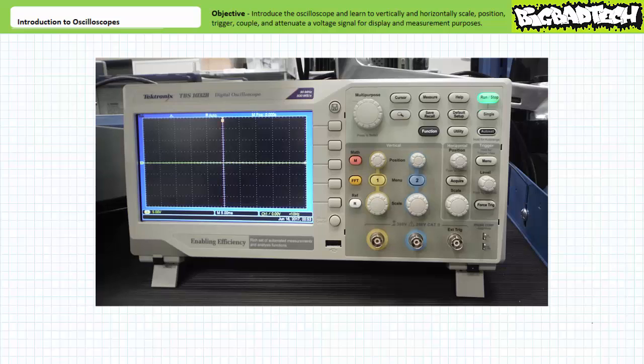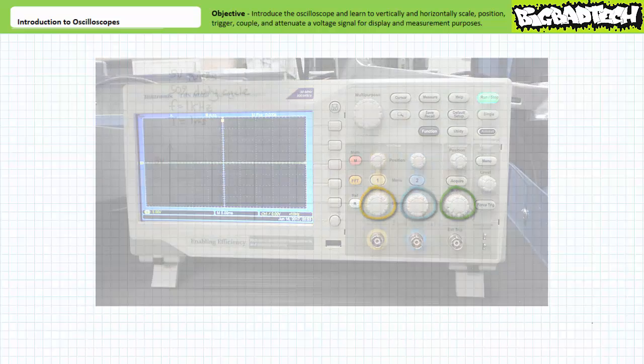In summary, an oscilloscope consists of a screen with volts on the vertical y-axis and time on the horizontal x-axis. Elements within the vertical group are used to adjust volts per division for each channel, and the horizontal group is used to adjust seconds per division for both channels. The triggering group and the function buttons. You are now hereby authorized to touch only the vertical scaling knob for channel 1, the vertical scaling knob for channel 2, the horizontal scaling knob, and nothing else.